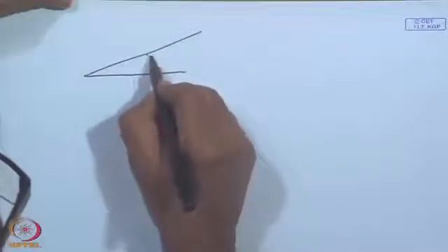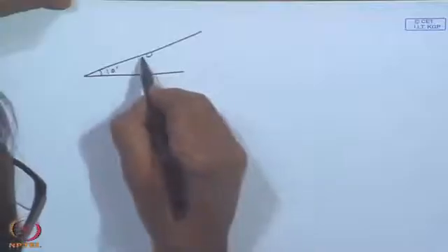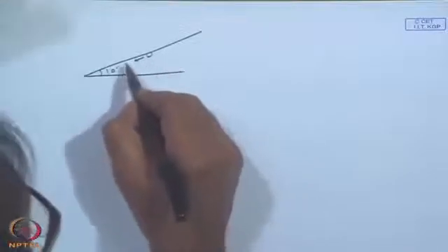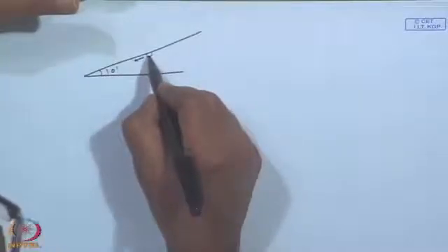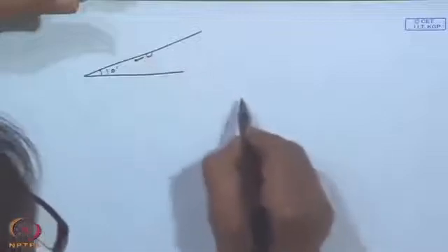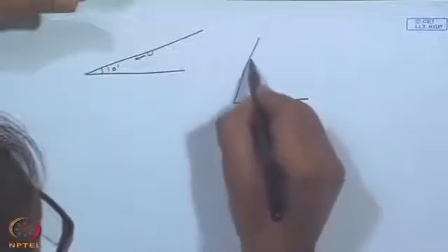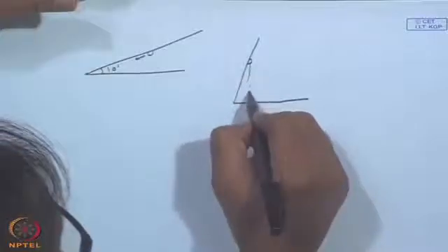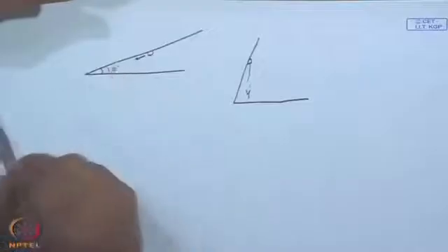if you find a drop, it tries to come this side because of gravity, right, some component in the vertical direction, and it tries to stick to this because of surface tension. And if you have a too large angle, it may come down straight and not flow along the surface.